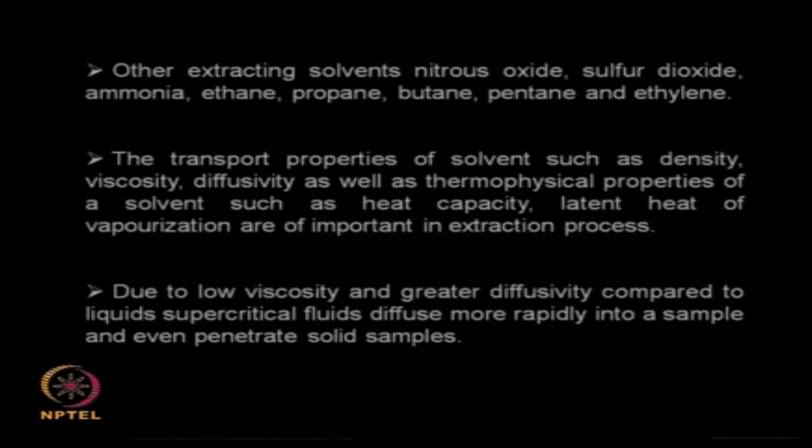Sometimes other solvents are also used for supercritical process, like nitrous oxide, sulfur dioxide, ammonia, ethane, propane, butane, pentane and ethylene and so on. The transport properties of solvents such as density, viscosity, diffusivity, thermophysical properties, heat capacity, latent heat of vaporization, all these are very important in an extraction process.